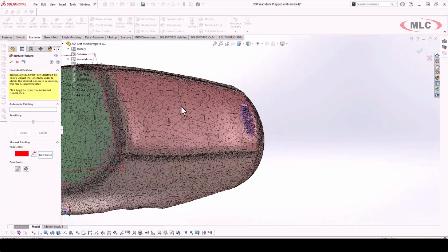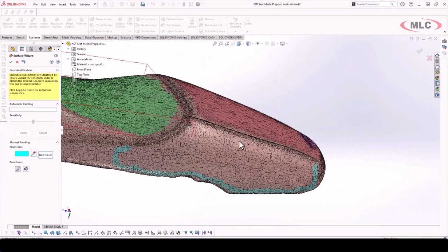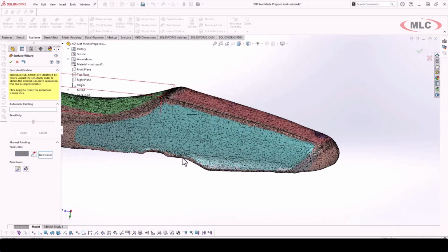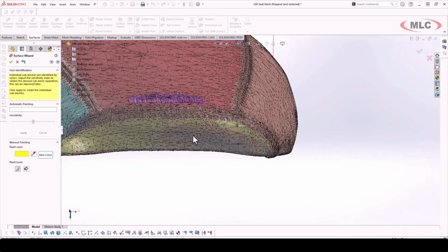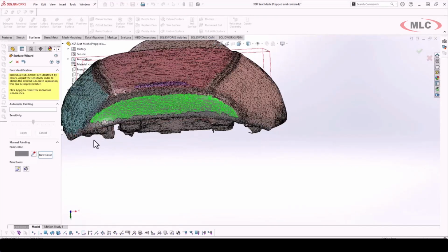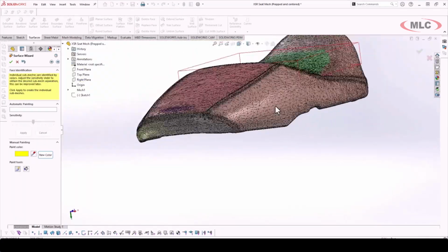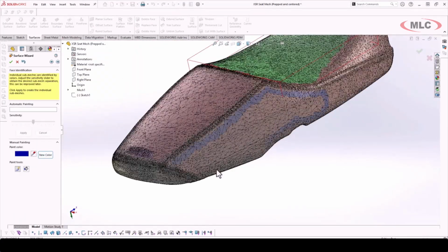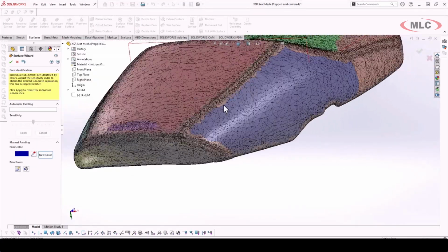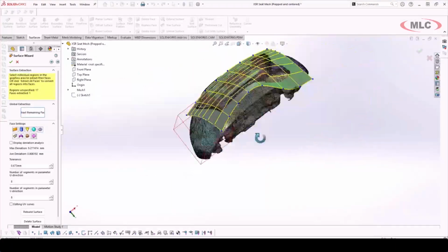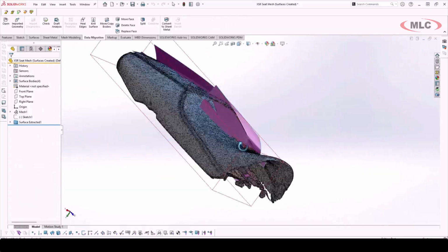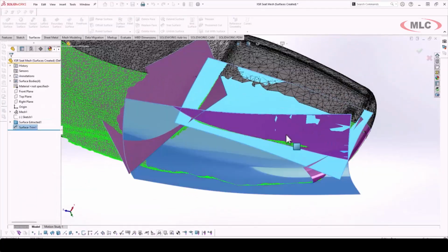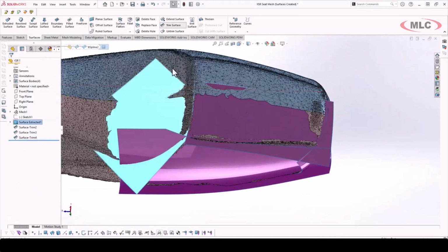I took the same approach as I did earlier, where I broke the surfaces up by the fabric seams on the seat, especially because I don't want the scan data from those seams to throw off the surface approximation. And so after highlighting those areas, I went through and created the surfaces using B-splines. And it worked pretty well the first time around, but I ended up going back and used symmetry to just build out half of the seat. That way I could mirror it later.